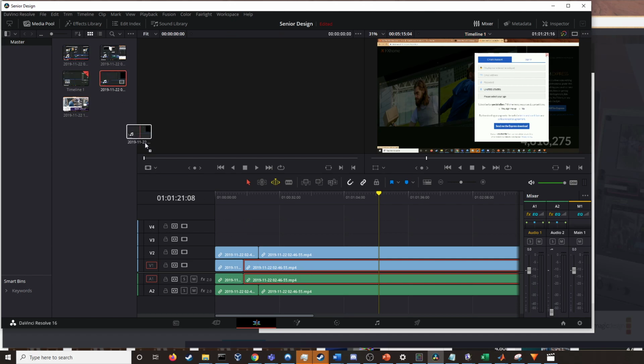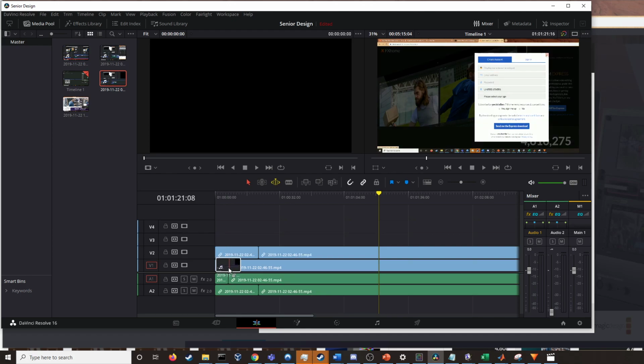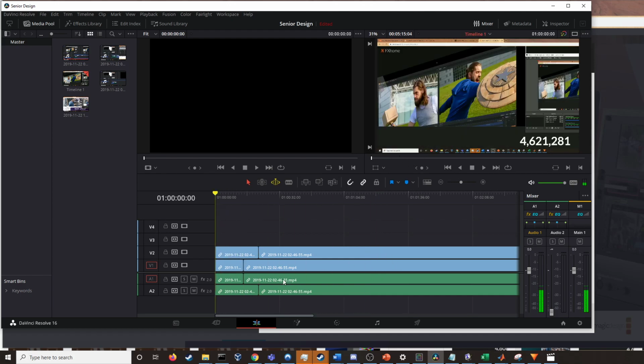So how do we get these videos in here? Well, we just end up adding to video 1, video 2, video 3. When you do have this situation running, it's basically just running concurrently. If I were to just start the video right now, it would play these 2 videos at once, audio 1, audio 2. You could mute them at different times, things like that. And you can change the audio as well. You really do just have a ton of different options you can run when you have these videos running in parallel.